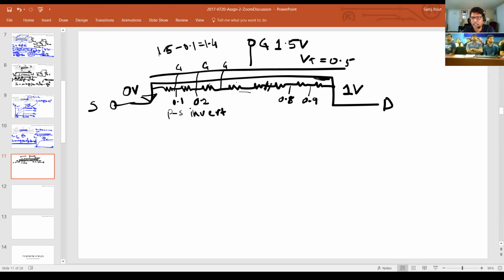So it's a continuous channel. You know, we actually lump it together as abstraction, but it is always a continuous channel. Now, obviously, for very small channels, it kind of looks almost continuous. I mean, abstracted, but it's really a continuous channel. So because the channel voltage is changing gradually, it looks as if these are 10 sources, which we have for 10 transistors, the way I have drawn. So like I showed before, I can actually draw this as 10 little transistors